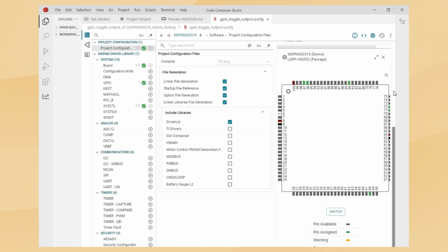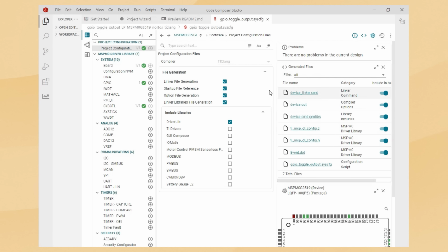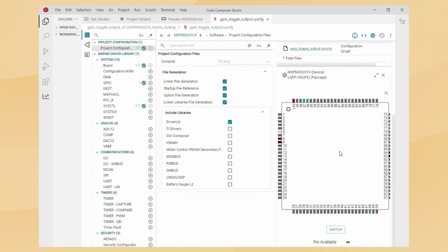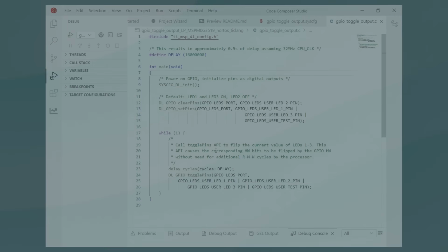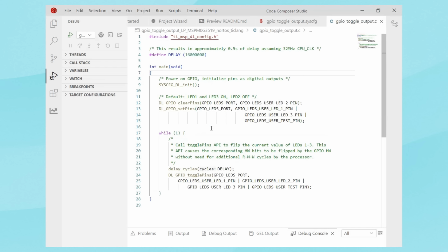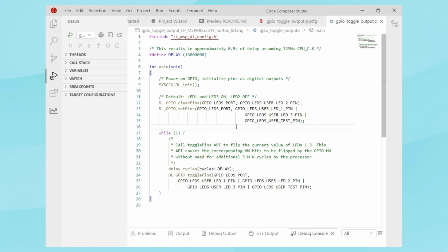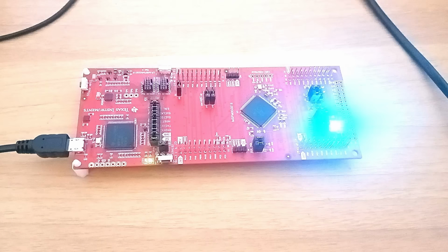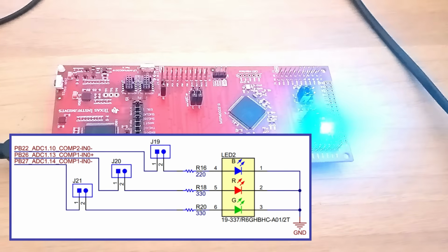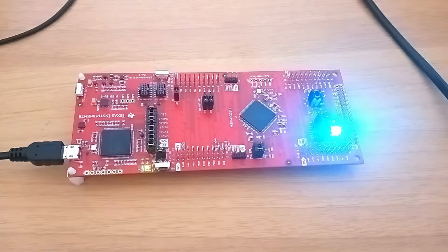After selecting the correct device, the system displays some features of the microcontroller, including the available and used I/O ports. The first example we'll try verifies the operation of the onboard RGB LED. Write the following source code in the editor and compile it by selecting Flash Project from the Run menu. After a few moments, the RGB LED will display different colors.